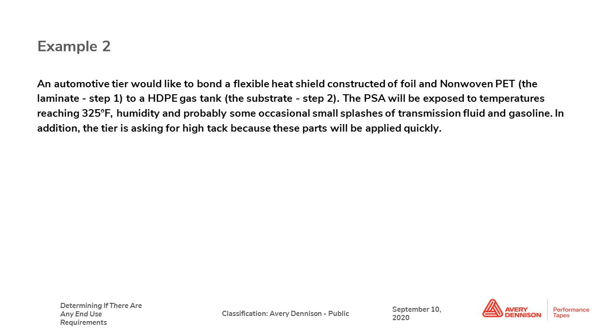The PSA will be exposed to temperatures reaching 325 degrees Fahrenheit. It's going to be exposed to humidity, and then probably some occasional small splashes of transmission fluid and gasoline. In addition, the tier is asking for high tack because these parts will be applied quickly. Wow, so a lot to unpack there.